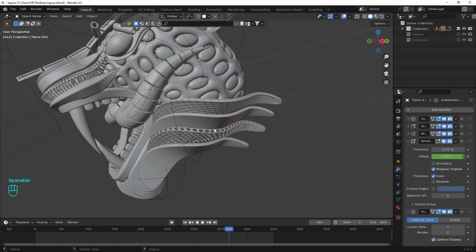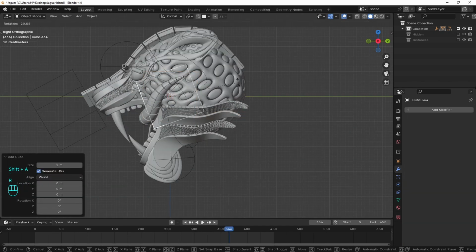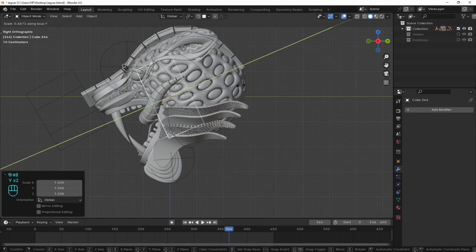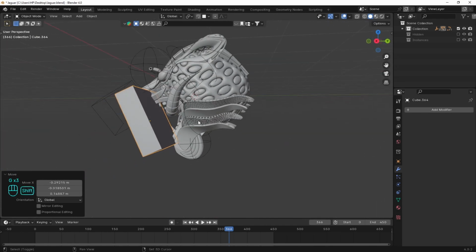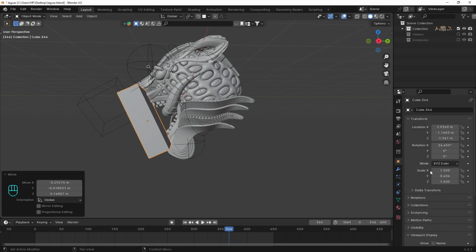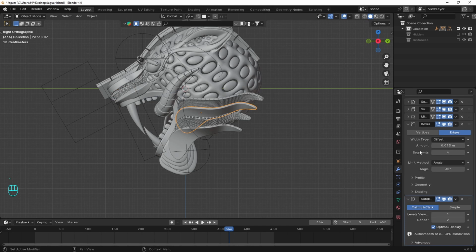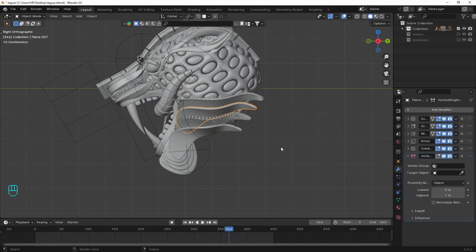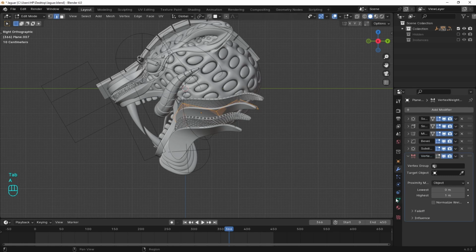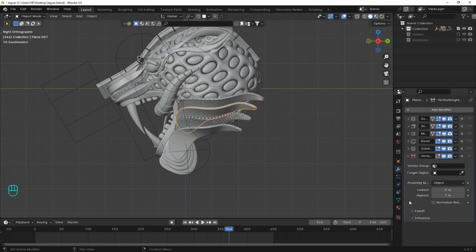For the third part, we're using again the proximity wave modifier to pull up some of the mesh. That's why it's the cube, we'll use it instead of the empty. Change the display to bounds to see what we are doing. Let's add the proximity. And for this we need a vertex group, so let's create and assign one with everything selected. Connect the modifier with the vertex group and the cube.